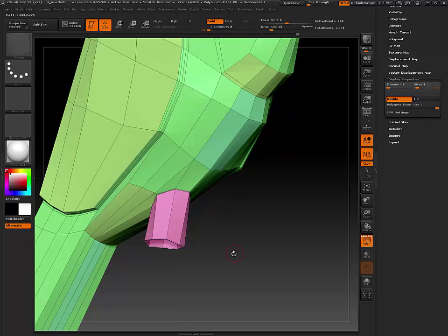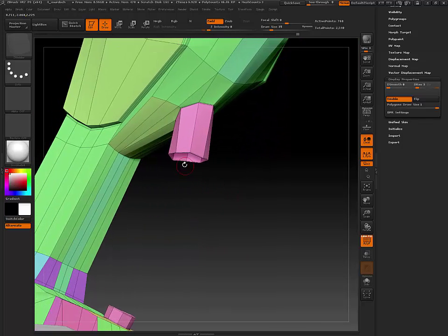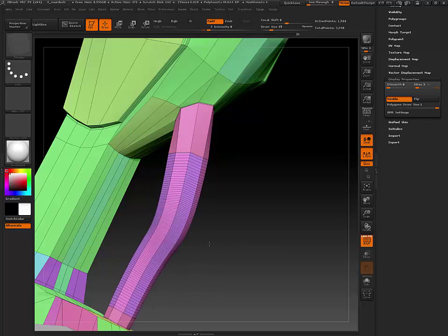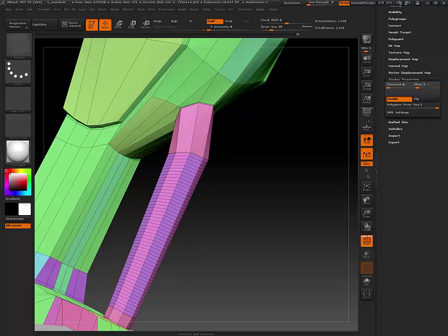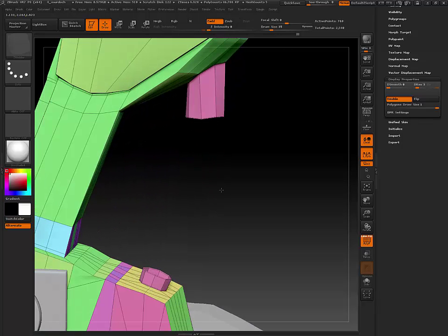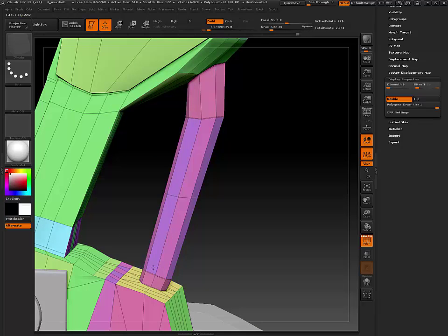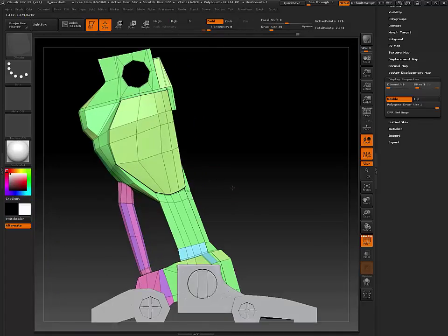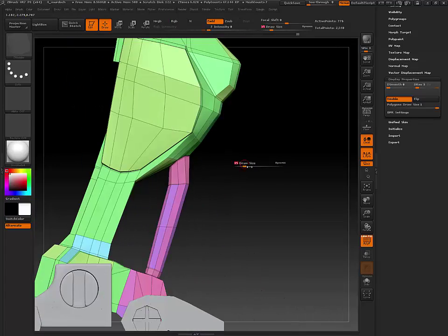I also want to show you another trick. Select the second edge, then hold down your mouse. You can add resolution if you go sideways while you're holding down your mouse. Okay, you can add more resolution. I don't need that much. I'll undo. Let's do it again. Yeah, here we go. Now it's looking good.